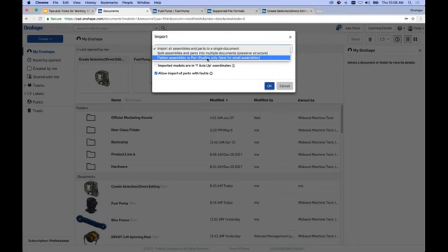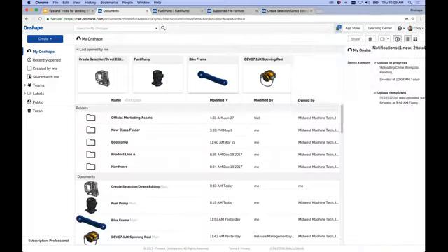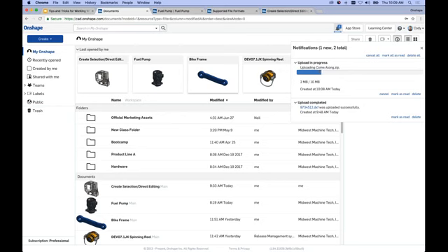I'm not generating a bill of materials or anything for this part. I really just need it in my assembly so that I can build up my part. So those are the import options. Very important to mention. I'm just going to choose the default, and I would say in most cases the default works just fine. I'll hit OK, and it's going to import my geometry.